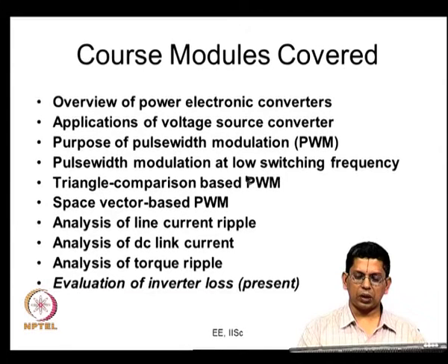That is why many high power inverters switch at rather low switching frequencies. You might have just a few hundred hertz of switching frequency, for example, whereas at medium power levels you can look at a few kilowatts and a few kilohertz of switching frequency, and at low power converters like MOSFET converters you may even think of 100 kilohertz.